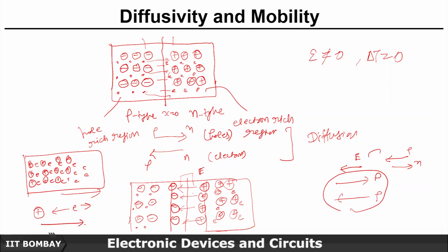So electric field is in this direction. Again, positive charge, negative charge, electric field is in this direction. Electron also wants to move in this direction because of the concentration gradient, but this electric field does not further allow their movement, and an equilibrium will be achieved at some stage. Okay, so this is how the internal electric field forms in the semiconductors. Because of this diffusion current, these carriers move from one place to another place. We'll talk about that in more detail when we talk about p-n junction diodes, and this distribution plays a very important role.